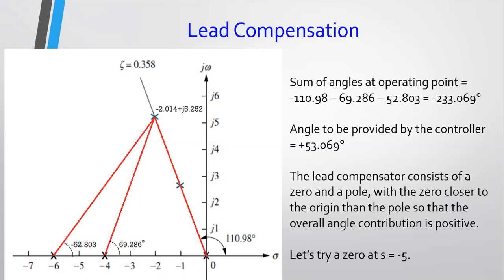Okay, so this is where I would say a bit of subjectivity is introduced, where you would need to first set a suitable position for your zero, then calculate the corresponding pole, and then do a simulation and cross-check: are you getting a suitable response for transient and maybe your error? If your error is increasing too much or you are not getting the proper transient, it simply means the dominant pole you're getting is not providing a suitable second order approximation, and you would need to choose other places for your zero. So it's a bit of an iterative process.